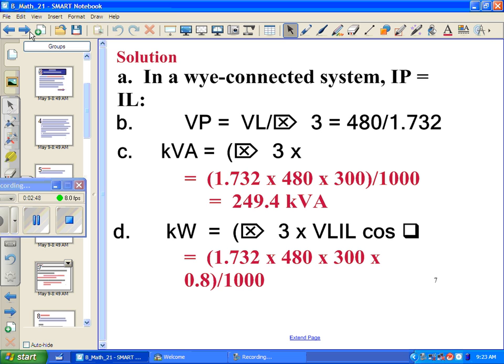I know that's easier for a lot of people, but phase voltage is equal to line voltage divided by square root of 3, which is kind of saying it backwards. I don't like doing it backwards like that because if you remember one of the formulas, remember that phase voltage in a Y times square root of 3 is line voltage. You can remember that, right?